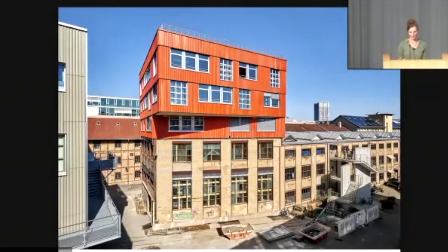So there are these two types of windows that we use. The larger ones come from a building in Zurich that was dismantled after 28 years. These were one of the first triple glazed windows, very high quality, thermally separated aluminum windows, triple glazed. And the other ones, with the little squares, are industrial windows that come straight from that site. With the first windows, we were able to make measurements while they were still in use. So we knew about the energetic value that they have, and we could then convince the city of Winterthur that this is the number we take into our energetic calculations.